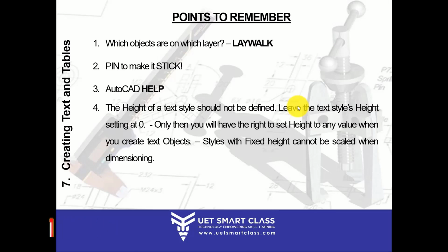Okay, now some points to remember. There are 4 points which I want you to remember this time. First is which objects are on which layer. There is a command called LAYWALK. Maybe I would have covered it, but I want you to remember this as a very important point.